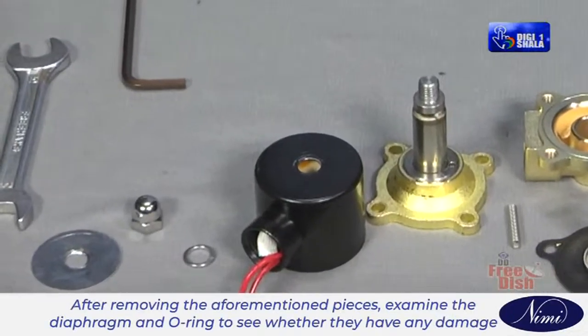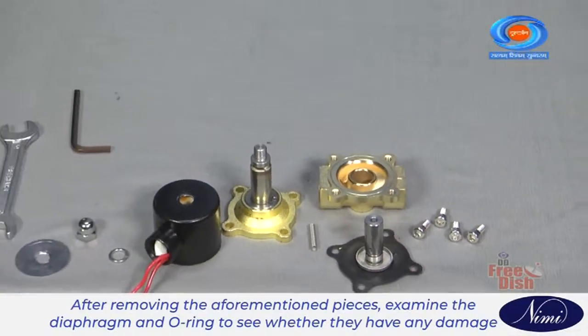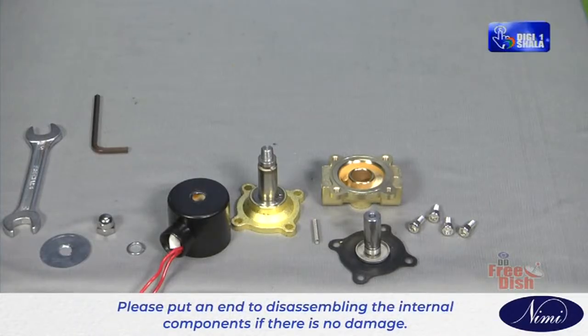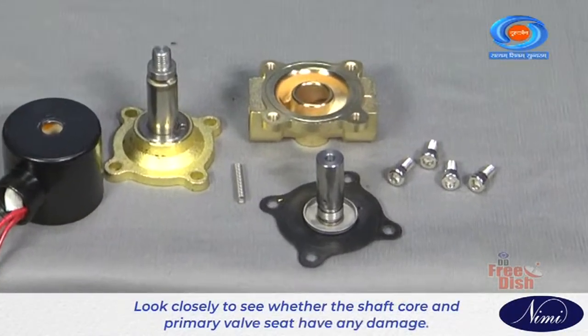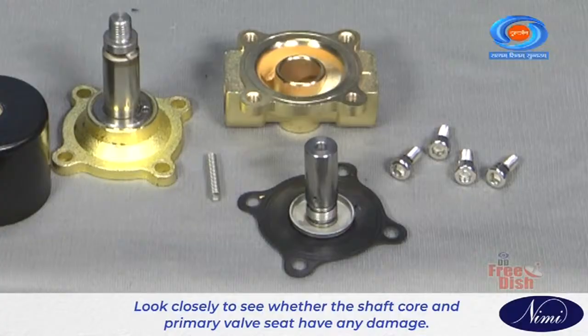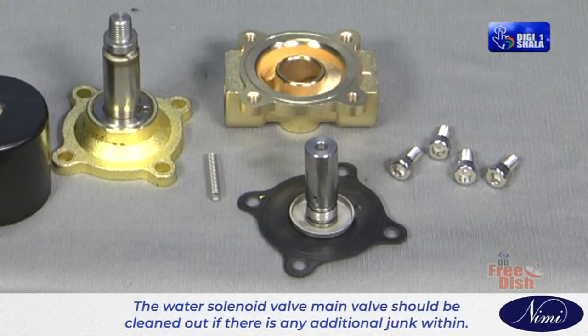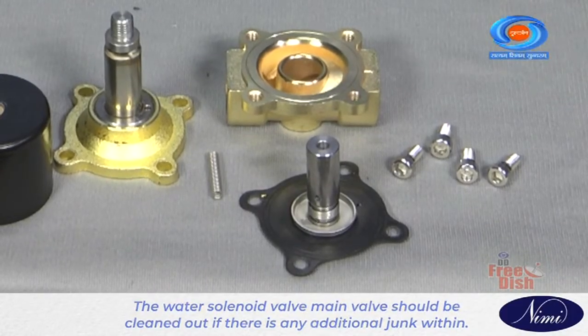Step 6. After removing the aforementioned pieces, examine the diaphragm and O-ring to see whether they have any damage. Please put an end to disassembling the internal components if there is no damage. Step 7. Look closely to see whether the shaft core and primary valve seat have any damage. The water solenoid valve's main valve should be cleaned out if there is any additional junk within.